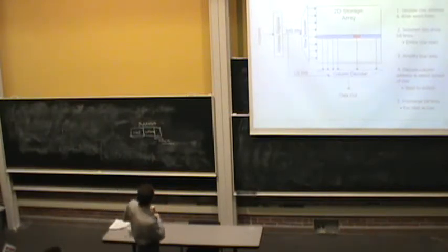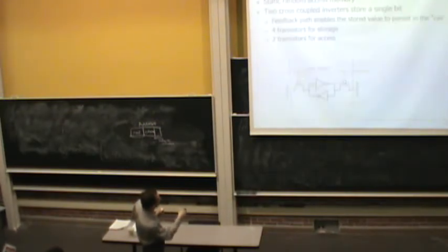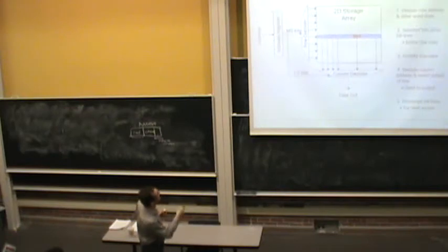So you take these row bits, if you will. They go through a row decoder, and get decoded. And once decoded, it enables the row select, or word line, if you will. This is also called the word line of the cells in the same row. So now you can read all of the cells within this row.